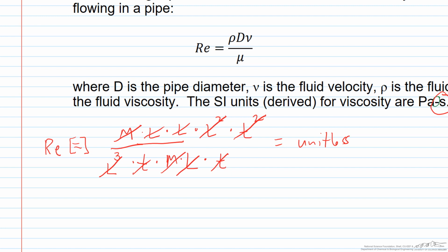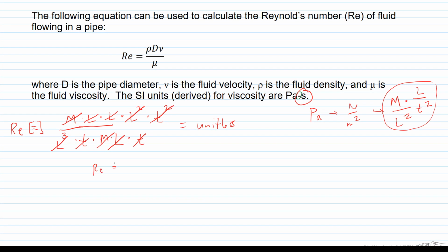Another thing that people typically do is they work with units, and I'll show you this in the next screencast. But we could do something like, if we had SI units, Reynolds number has units of, and I would write kilograms per cubic meter for density, times meters for length scale, times our velocity, which is meters per second, and then we divide by viscosity, and viscosity is Pascal seconds. We can do a couple conversions here, and you'll review more about this in the next screencast. But we have Pascal. A Pascal is a Newton per meter squared, so I'll put this meter squared on the top.